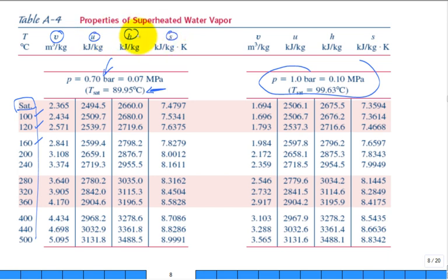How come they don't have h_f or u_f and u_g? I mean, why don't they have two entries? There's no longer a quality. It's superheated vapor. It's beyond. So sometimes students will try and calculate a quality in the superheated region. They'll get a number of about 1.3. There's no quality. Quality is only used from saturated liquid to saturated vapor. If you're starting to get qualities below 0 or above 1, look for an error. Okay?